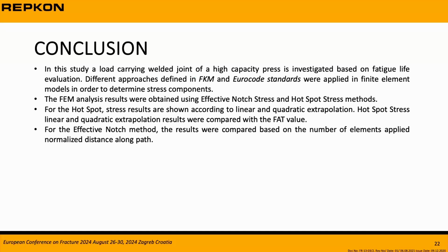Conclusion, we talk about the different approaches for the welded joint of the high capacity press investigated based on fatigue life evaluation. We talk about effective notch stress, hotspot stress method, and then we calculate in the finite element model and discuss further results. For the effective notch method, the results were compared based on the number of elements applied along normalized distance along the paths. Thank you for your attention.